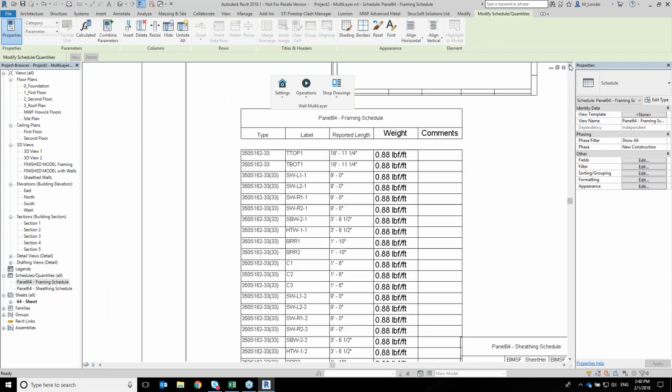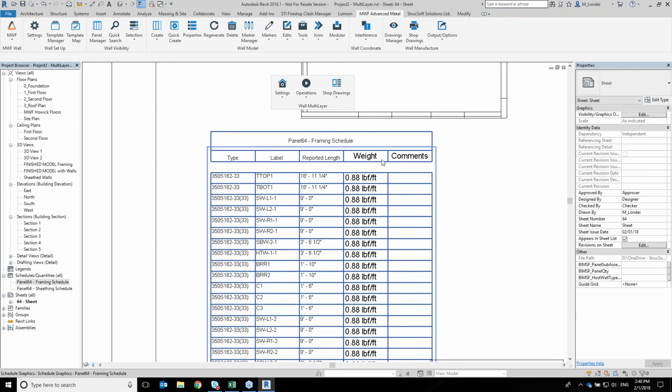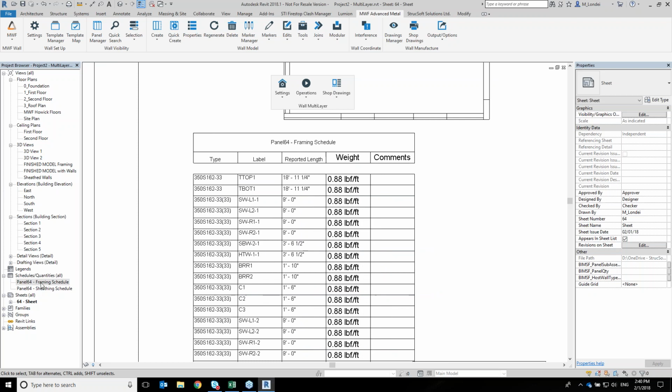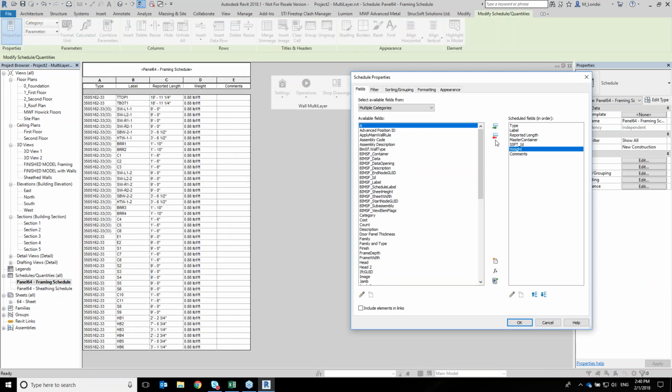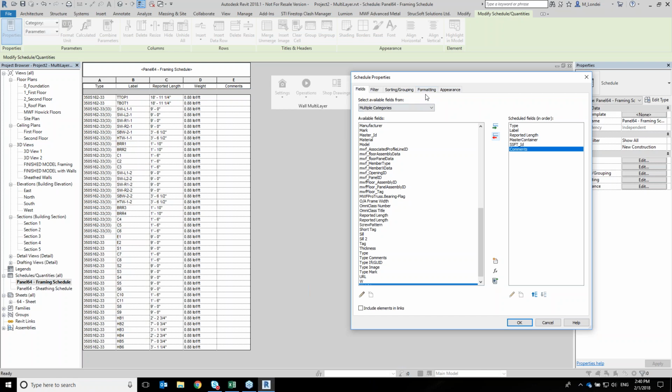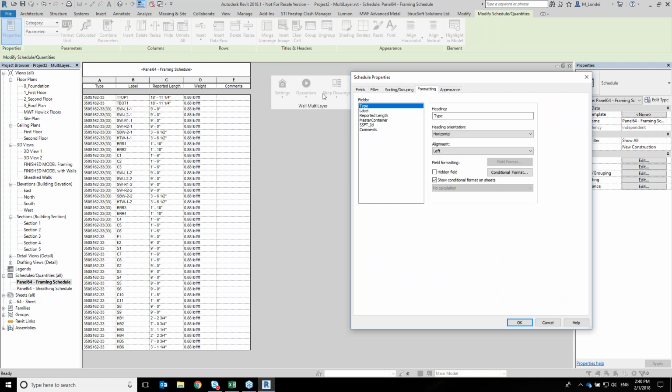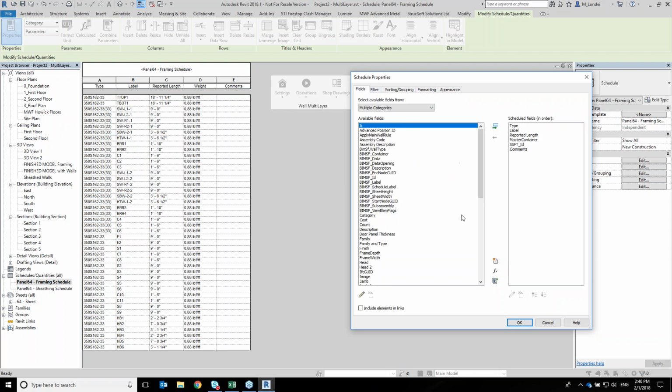But if I go back into my shop drawing, those elements all exist here already. Again, I've brought in the weight, but I need to put an equation on there. But we can go ahead and easily do that within our Revit schedules because we know how to use, right here, we can use a formula, length times weight, to get the member weight. Oh gosh, excuse me, folks.